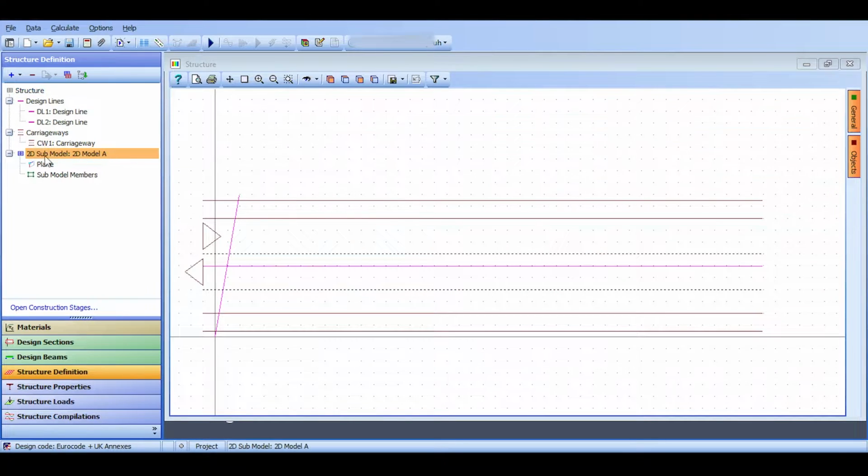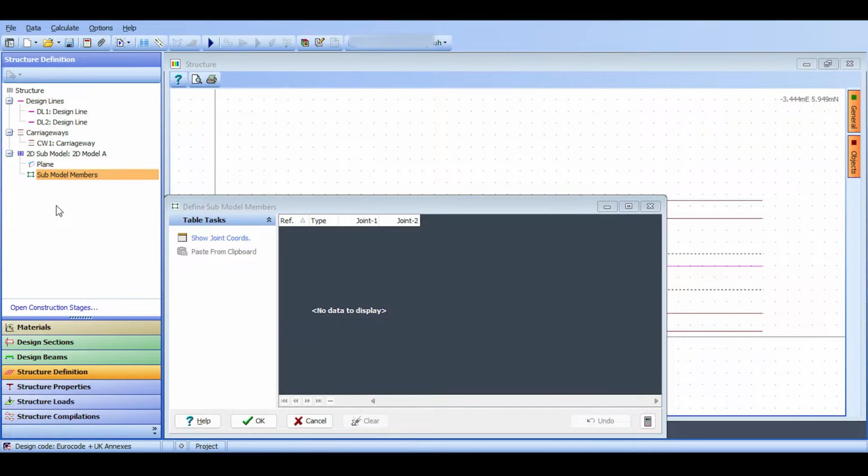When you click on that, it adds the model. Now, of course, it asks you how the model would look like because you haven't defined anything for the model. Now, in the model here, I will start defining my submodels. Because I have a 2D model, I need to define my submodels that define each one of those spans. Now, when I click on submodel, it seems I can't do anything. This is a little bit strange, and follow me.